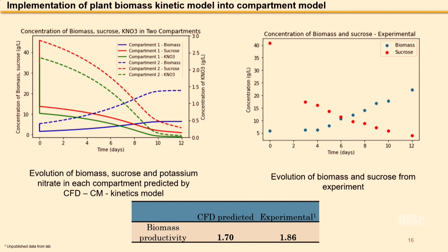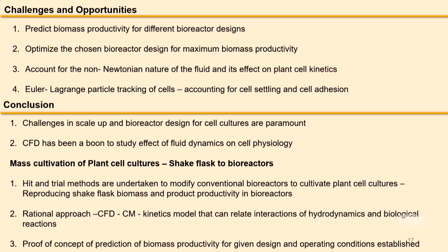Now we are looking into improving this model to see how the biomass and substrates vary with respect to more specific zones, using more than two compartments. We were able to establish that this CFD model, when linked with the biomass kinetics equation, can predict the biomass productivity for a given hydrodynamic condition.